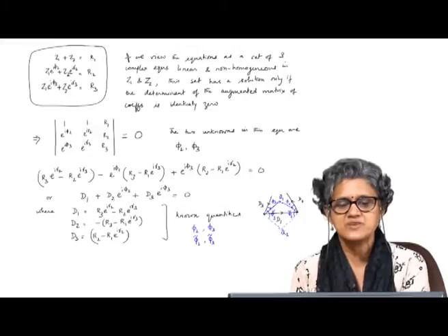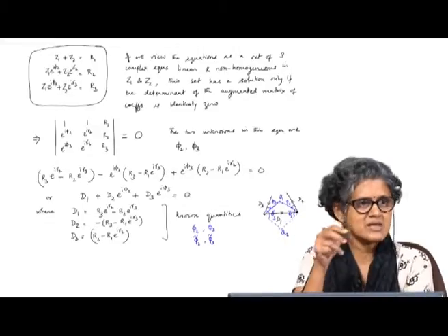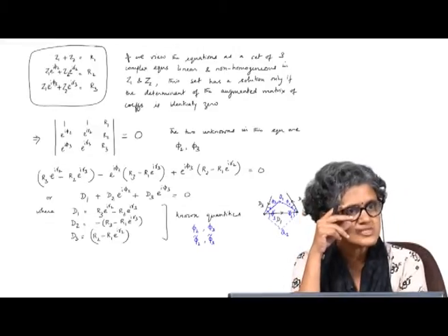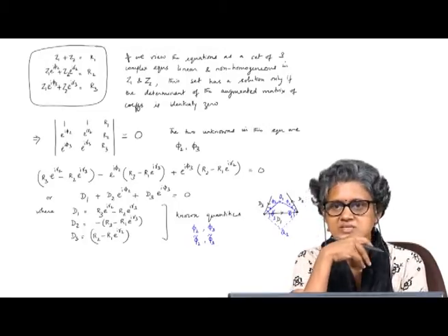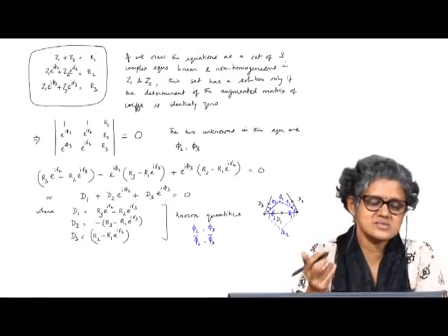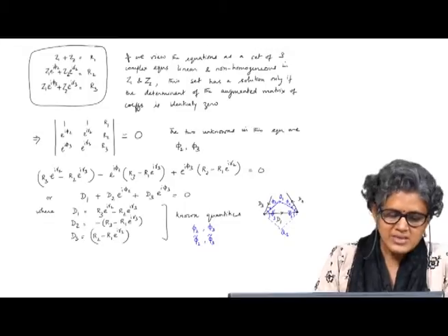You specify the fixed pivot by means of, so minus R1 is your specified fixed pivot with respect to your coordinate system. So, this is the way you would use the dyad method to solve for a specified fixed pivot, design a 4 bar.